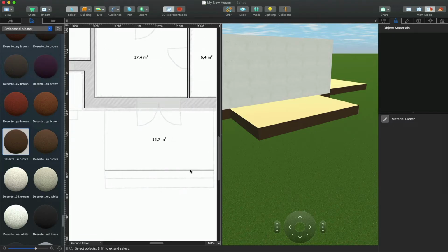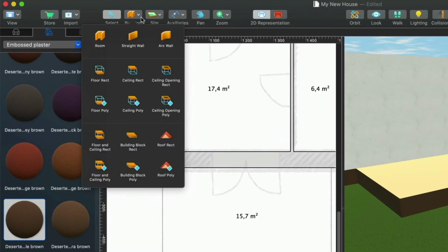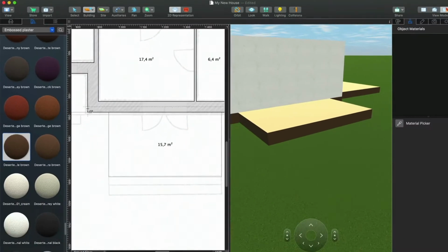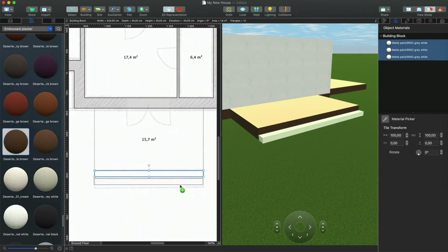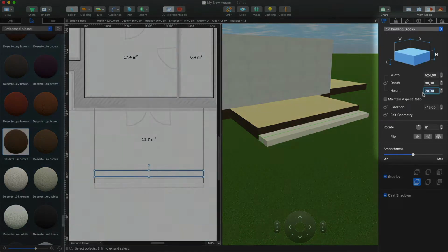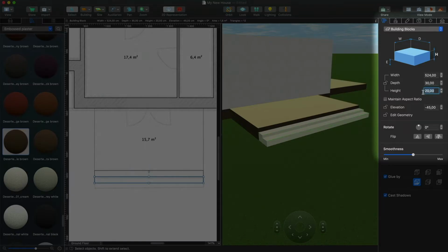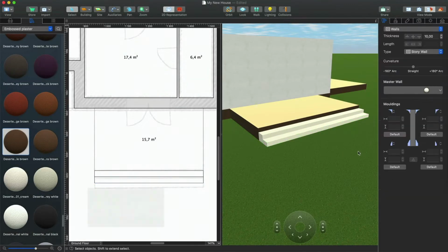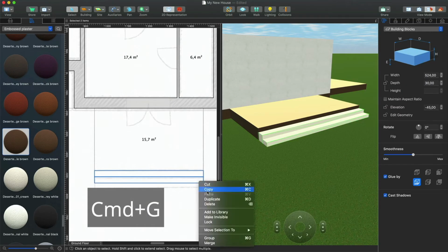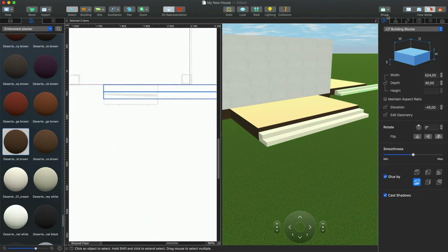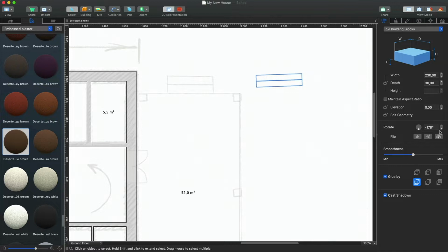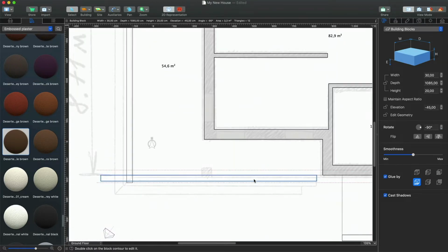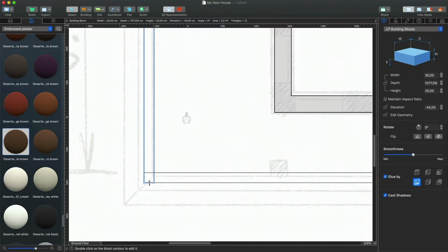This tool can only be found in the Pro version. As an alternative, you may utilize objects from the Shapes category of the Object Library for this purpose. Draw the steps with the tool and change their height in the inspector. For convenience, you can group them with the Command-G shortcut. To draw the intersection in the corner, double-click on the building blocks and move the control points to change the shape of the steps.